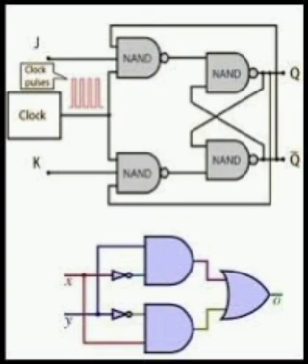Non-arithmetic circuits. Multiplexer is a combinational circuit which has many data inputs and a single output depending on the selector control input. One of the input lines is transferred to the output, hence it is known as a many-to-one circuit, universal logic circuit or data selector circuit. The selection of a particular input line is controlled by a set of select lines. There are 2 power n input lines where n is the number of select lines.